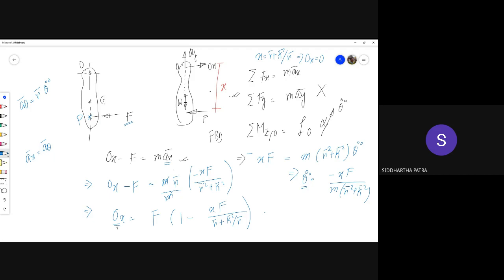So this is another significance of the center of percussion, that if you apply a horizontal force in the equilibrium configuration of the pendulum, there is no horizontal reaction at the pivot point. But this one we are not using in today's experiment. So the last assignment question was, what were the different significance of center of percussion? We just discussed two, and the second part of that question was, which one did we employ in our experiment? The answer to that is the first part.